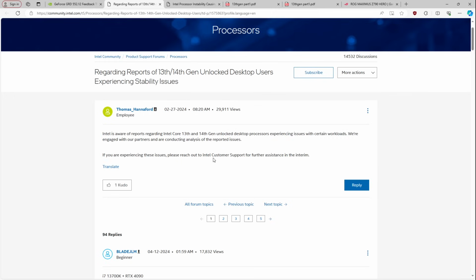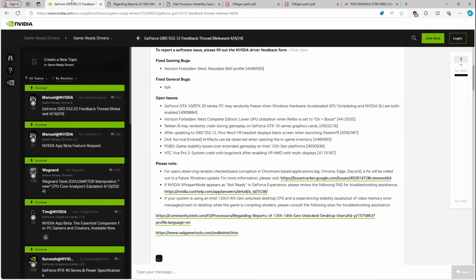And then AMD, after the 3000 series issues, where the 3950X was sort of the most egregious example of not hitting the single core boost ever, we haven't had that issue since with AMD CPUs. Now you do still occasionally see it. I have heard of people getting, say, a 5950X where it won't be stable unless you give some of the cores a positive curve optimizer offset.